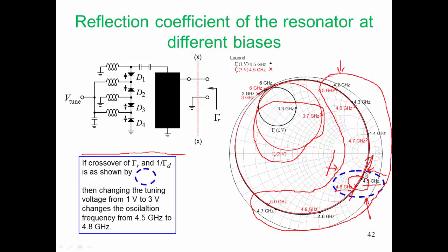Now that conductance of the active network we design so that it is independent of frequency. And so it is essential for us to have a conductance of the resonator network that is independent of frequency. Well, we're not perfect, but we are very close. We are almost on a constant conductance curve.